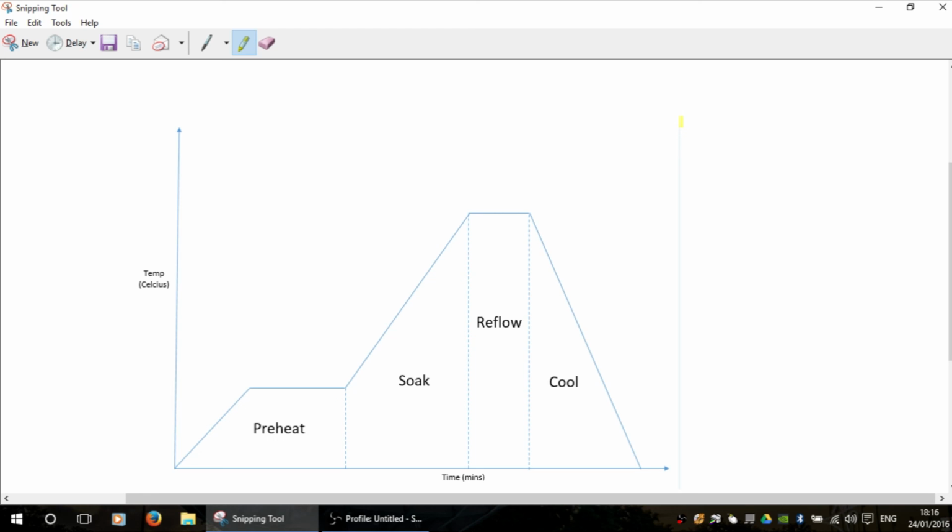And as we also said earlier, don't forget about those different chip types. So, the silicon substrates, the plastic substrates, BGAs with integrated heat sinks, with exoskeletons, all of these are going to respond differently and each will need their own profile. Even BGAs of the same type. So say you've got an Xbox 360 GPU and an NVIDIA GPU die from a PC graphics card. They can both look identical, but both can respond completely differently to the same rework profile. So these all really need to be honed on their own, on your machine, by you.